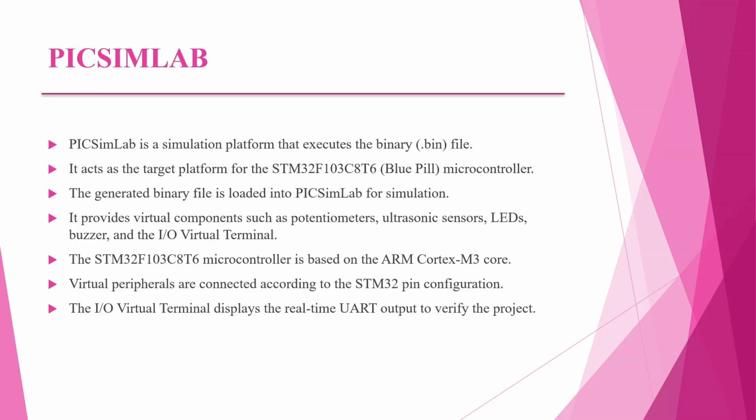PicsimLab is a simulation platform that executes the .bin file, as I said before. It acts as the target platform for the STM32F103C8 Blue Pill microcontroller. It provides virtual components such as potentiometers, in which we can change acceleration, brake, SOC, and temperature.